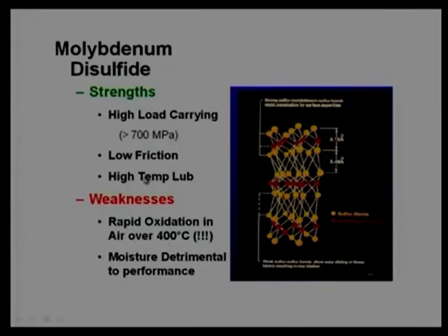That is why we say that it is a high temperature lubricant, and a temperature even up to 1000 degrees centigrade is not a big problem for molybdenum disulfide. However, there is a problem with moisture. If the environment has a lot of moisture, then molybdenum disulfide will not get attached to the surface very strongly. In that situation, it will get dislodged or removed from the surface, and that is a problem for molybdenum disulfide. With excessive humidity, we cannot use molybdenum disulfide as a lubricant.